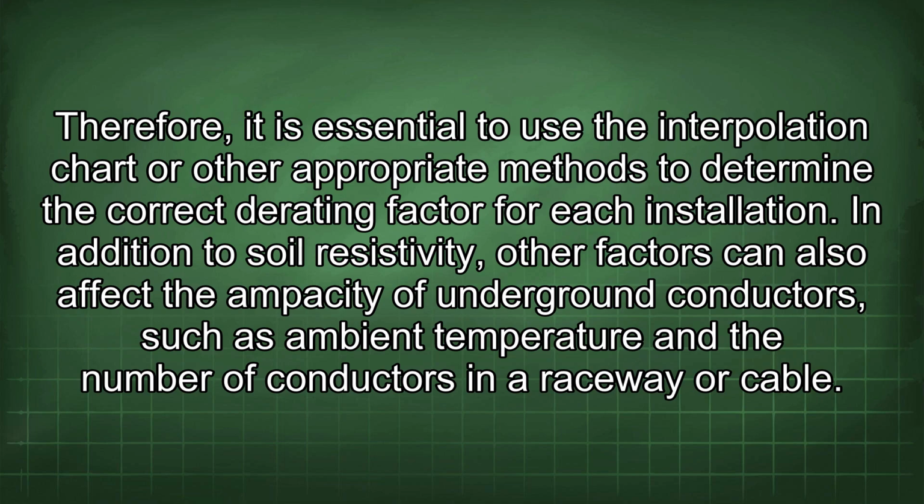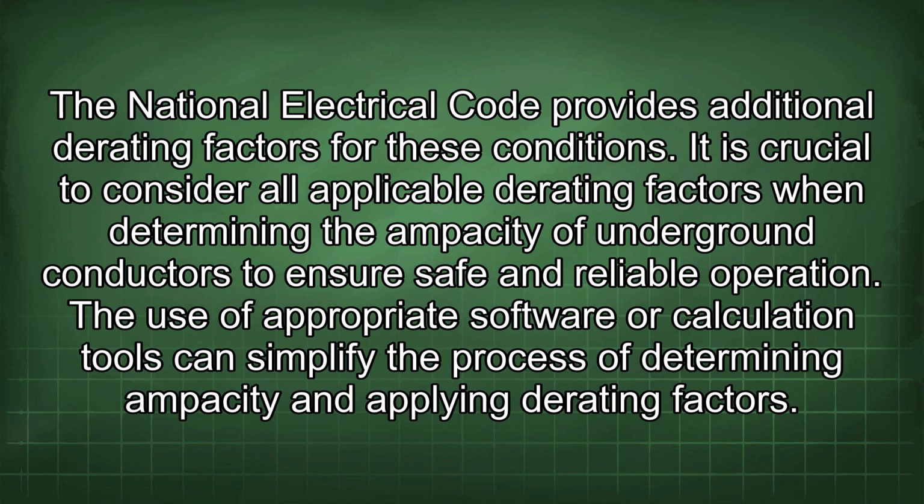each installation. In addition to soil resistivity, other factors can also affect the ampacity of underground conductors, such as ambient temperature and the number of conductors in a raceway or cable. The National Electrical Code provides additional derating factors for these conditions. It is crucial to consider all applicable derating factors when determining the ampacity of underground conductors to ensure safe and